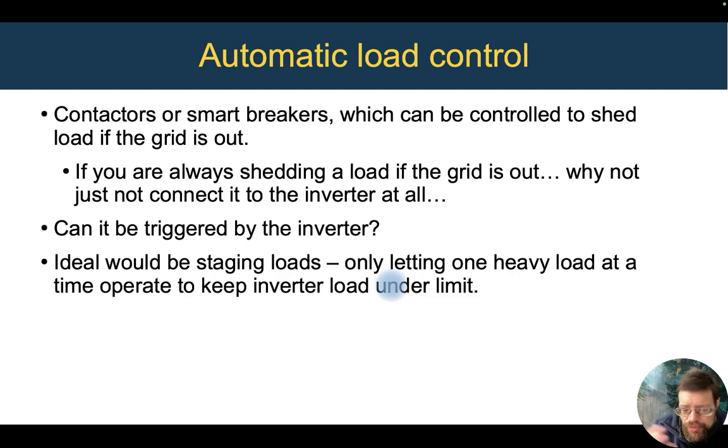And depending on which ones they are and what kind of control scheme we have, we always run into the issue of, can we be triggering those from the inverter, or does it have its own control? There's a lot of different smart load panels out there, but really integrating them with the inverters is still very on the cutting edge and involves a lot of time figuring out communications and interfacing between them at this point. So I don't consider that a really good solution yet.